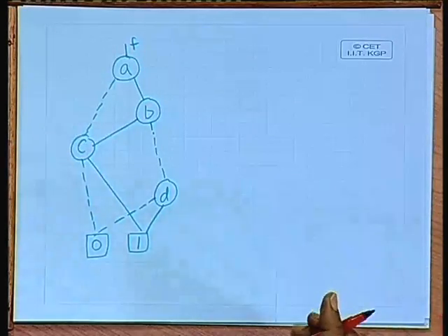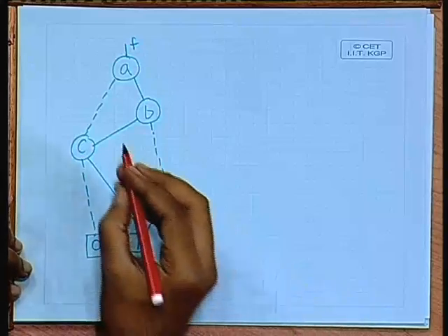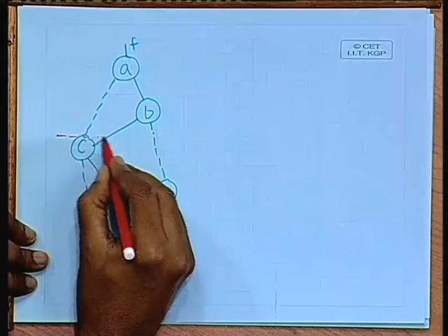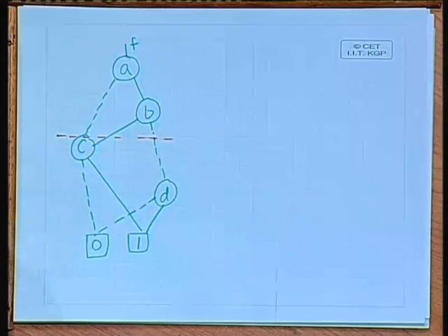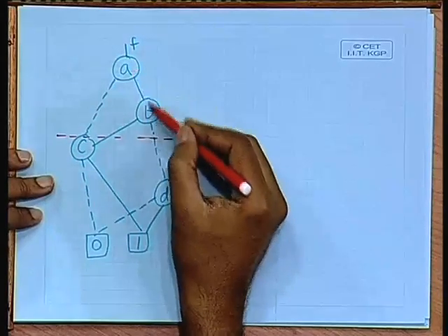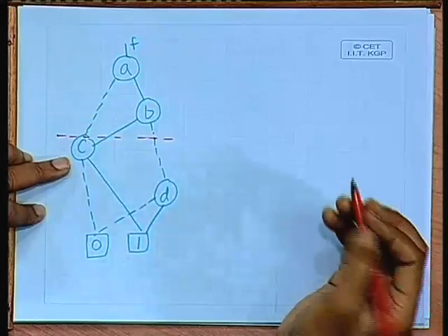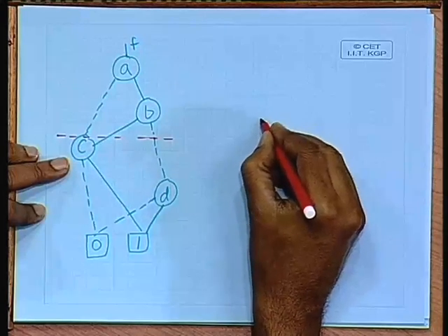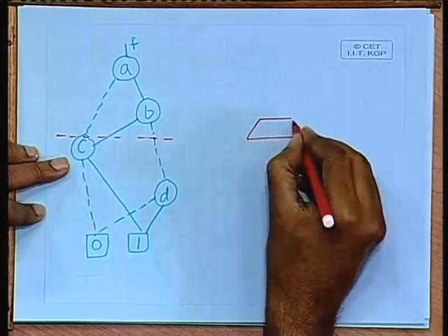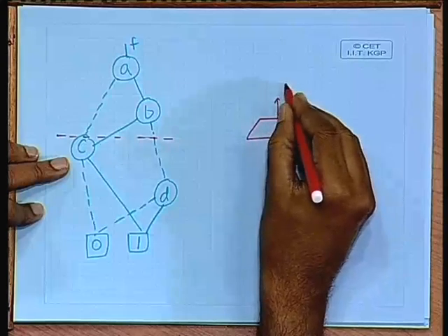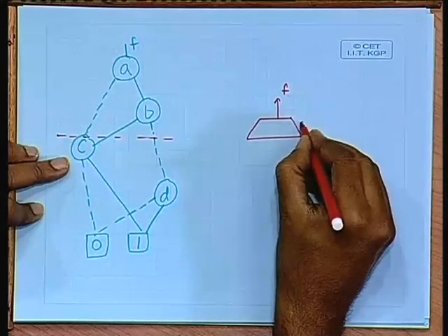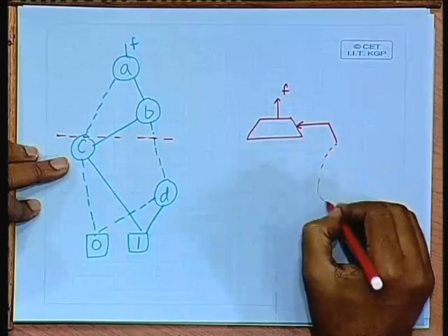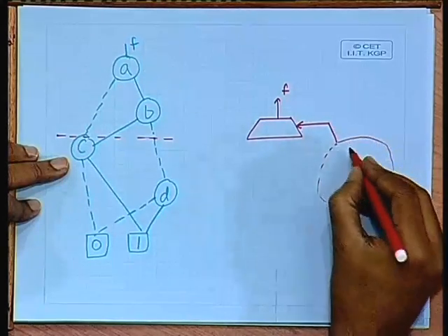What we can do is that we can cut this, say, at this level. So, after A and B we can cut this at this level, and we can have a realization like this. This is a multiplexer whose output is F, and the control input which is feeding, I am showing it in abstract term. This is a circuit which implements